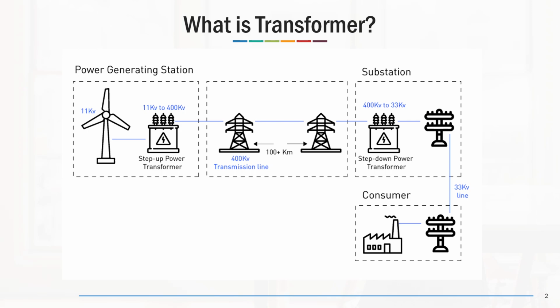So if we have high current, we have a lot of losses and also a lot of voltage drop. So before sending the power to very far locations, we increase the voltage by step-up transformers. Because the power is constant, when we increase the voltage, the current will drop a lot. So we avoid further losses in the transmission lines.